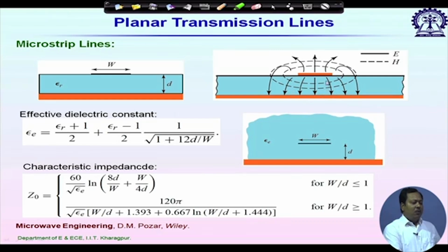If I look at the microstrip field lines, we also have these perpendicular field components. So the surface wave TM0 mode will be easily excited by a microstrip line. Now, the TM0 mode does not have any cutoff frequency, so we can't avoid this TM0 mode excitation.